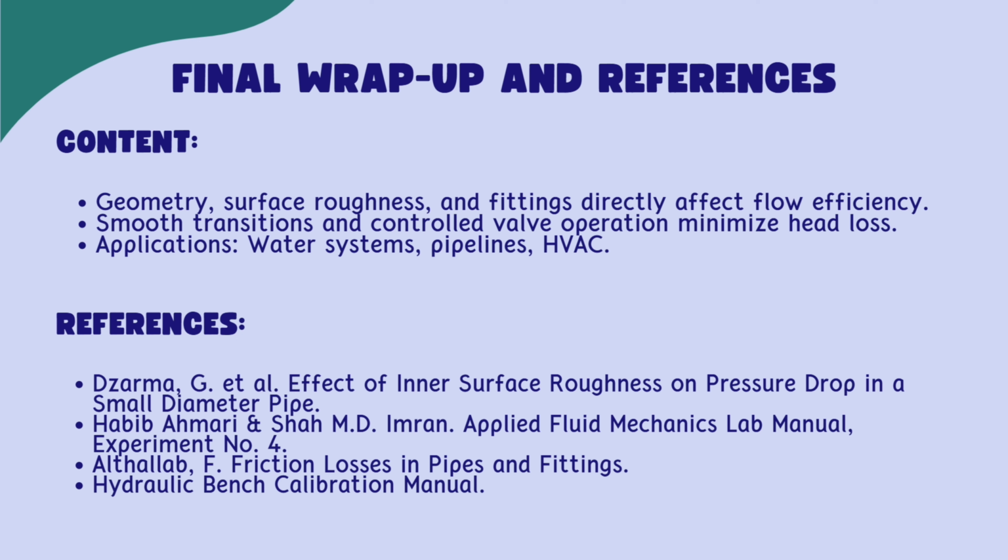So, in conclusion, our experiments show how every detail, from surface texture to shape, affects pressure and energy. Smooth and gradual designs ensure efficient flow, lower head loss, and energy savings. These insights are crucial for designing pipelines, HVAC systems, and hydraulic networks.